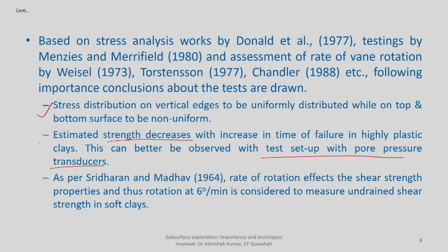As per Sridharan and Madhav, in 1964, the rate of rotation can also affect the shear strength properties. The previous point was based on the pore pressure induced related to the rate of rotation. This is telling that if you rotate it very quickly, you will end up underestimating. If you rotate it very slowly, then it is vice versa.